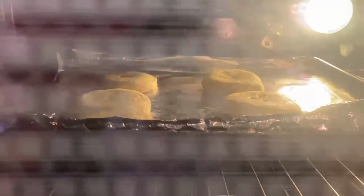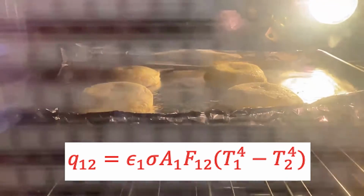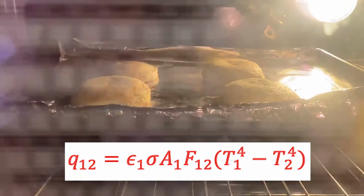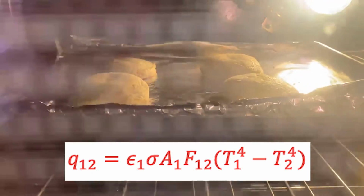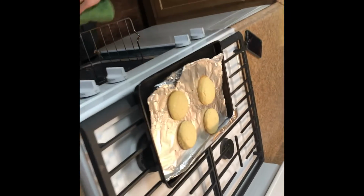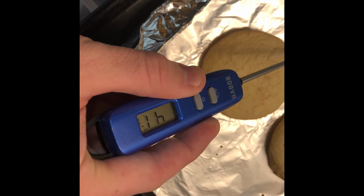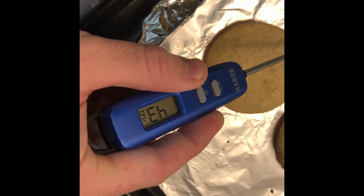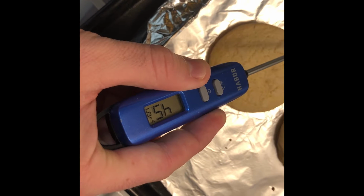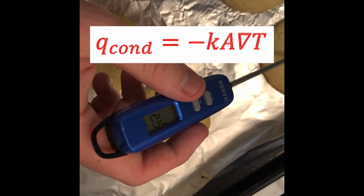into the baked cookie. We can analyze this heat flow through the Stefan-Boltzmann law, assuming that the cookie perfectly absorbs the heat of the oven. Calculating the area of the cookie and measuring the temperature of the cookie and the oven, the rate of heat flowing through the cookie can be calculated. However, not only do the cookies absorb the heat, but so does the pan. This creates a conductive heat transfer effect, as heat is absorbed through the bottom of the pan and upwards. Taking measurements of the temperature of the pan and cookie, as well as using a cookie thermal conductivity, the heat flow through the pan can be calculated via Fourier's law of conduction.